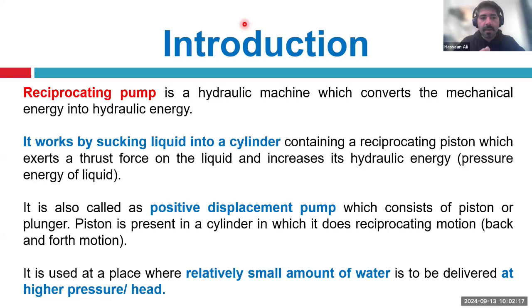So the reciprocating pump is there to transfer fluid from one place to another by increasing the pressure of the fluid. That's why in very high pressure applications, you will see a reciprocating pump and not a centrifugal pump. Although centrifugal pumps do provide a pressure increase as well as a high flow rate, they do not provide the same pressure increase that you would require for your application. It is also called a positive displacement pump. Whenever you hear about a positive displacement pump, just picture a reciprocating pump.